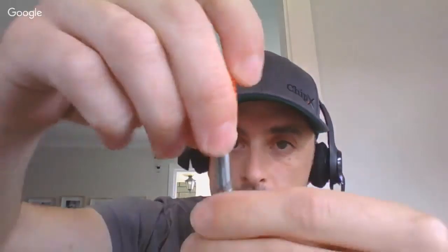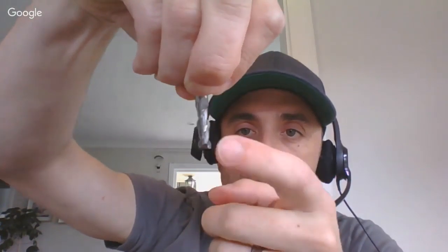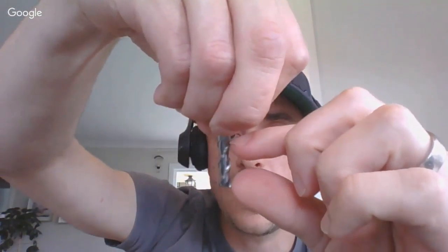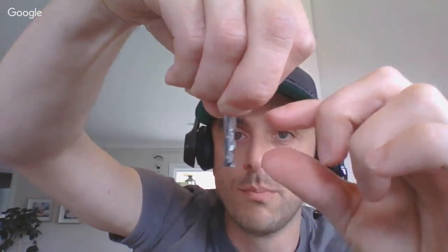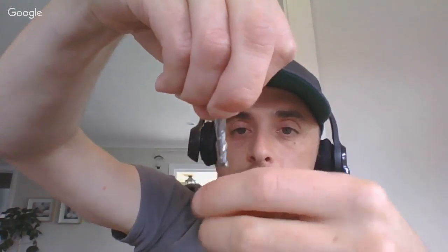But okay, so one of the things with adaptive clearing, right? There is a detail where if you've got a very rigid tool holding setup, and there's not a lot of ability for the tool to be misaligned angularly, then by having the tool running quite deep in the cut, the load is spread over a large part of the flute, and your moment arm that's trying to rotate that spindle is less, so you can get a more stable cut, and you can obviously remove material a lot faster.